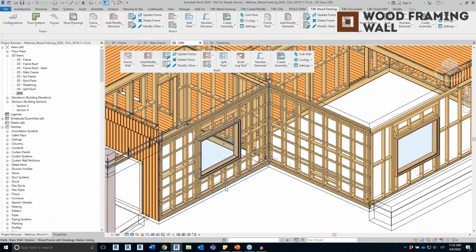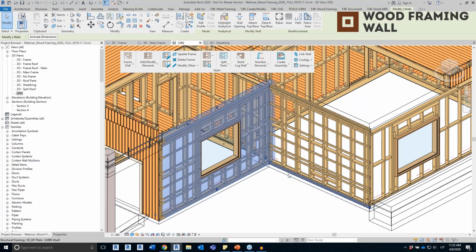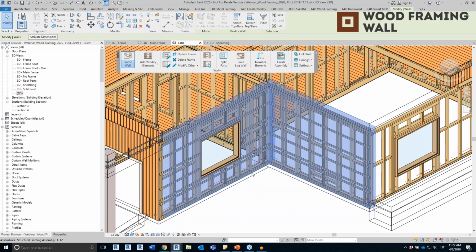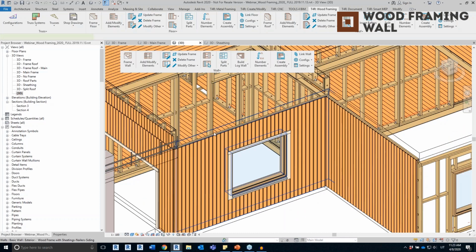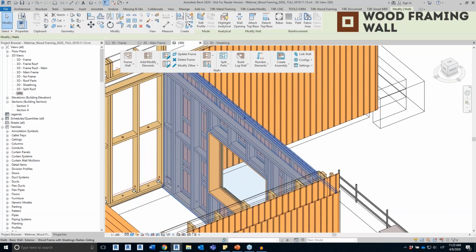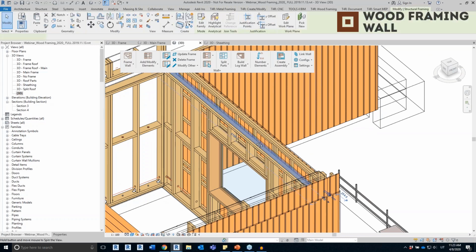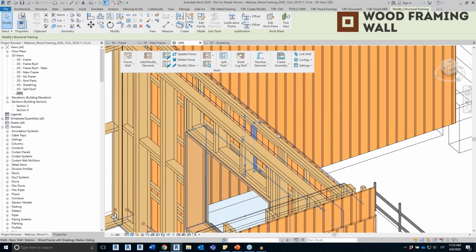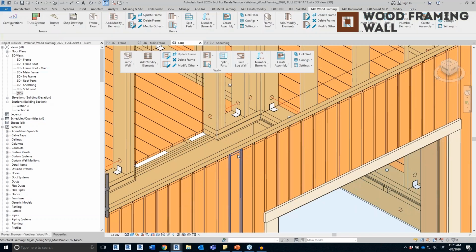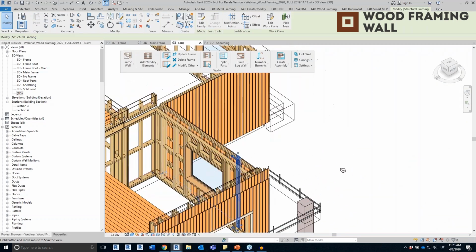And finally, I can also add the siding and my panels will be complete. So you can see that the main frame is lower for the supports of the floors, and then the nailers extend higher so that I would have elements on which you can add the sidings.